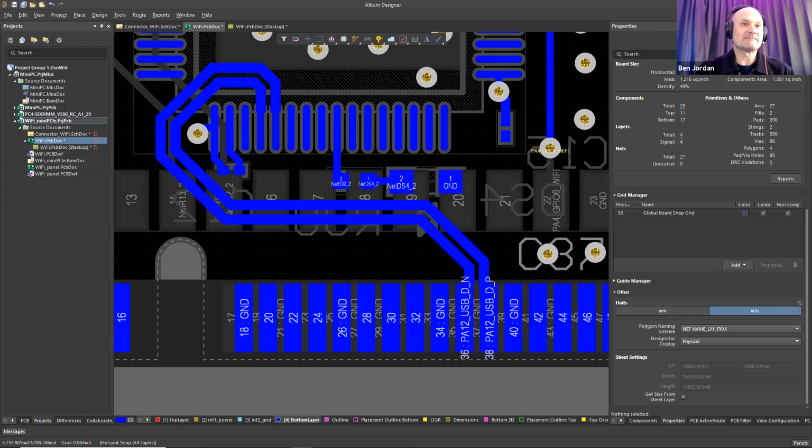You can make it that, but if it's 10 mils wide and the gap is 5 mils and the other trace is 10 mils, and you have a dielectric above the plane that's 8 mils, well, you can have 10 pixels, 5 pixels, 10 pixels, and 8 pixels. Because the field solvers don't care about mils, they care about relative distances. That's the beauty of these kinds of calculations, they're all about relative distances, and you can scale up or down.